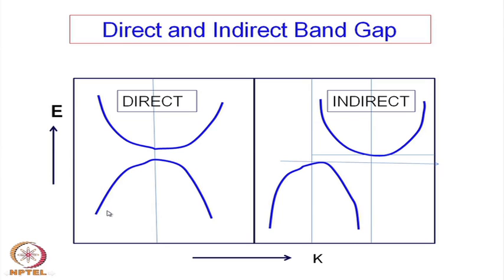Okay. And so, this is a continuous energy band, where continuous energies are possible, whereas this is discontinuous, that means these are forbidden energy levels, including this small gap. Along this direction the gap is more; as you go from this to the right or the left, the gap is increasing, but the minimum gap may be somewhere here. When we define the band gap or forbidden energy levels, we always talk about the minimum gap.